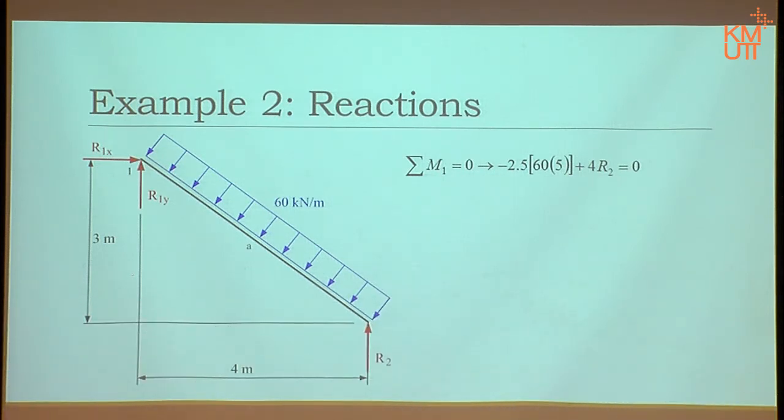Now the second part is R2. R2 is not in inclined angle. R2 is just vertical. Therefore, 90 degrees distance is horizontal, meaning from here to here, 4 meters. And then we can have R2. If you take component, it will be much longer, believe me. It will end up the same answer though. So it's up to you. Next, sigma fx, sigma fy will give you other parts.